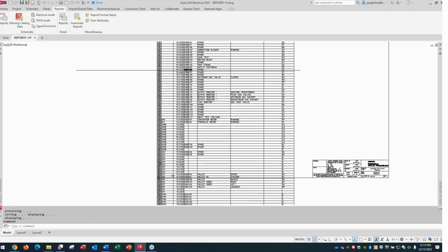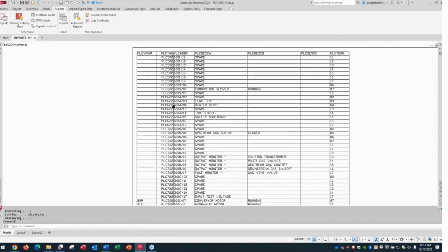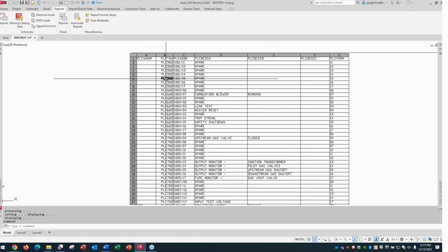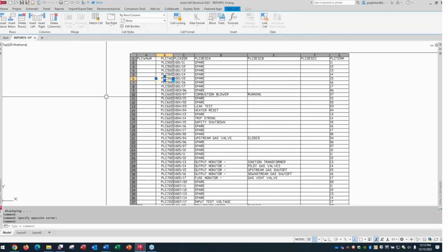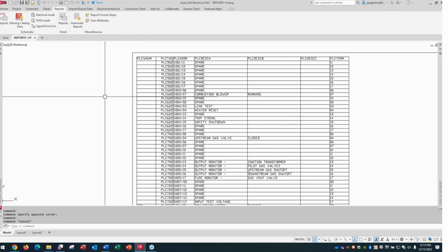This time, the text size is set to 0.18. So you can see what's very important here, which, you know, this part is not real intuitive as far as the software is concerned. Text size, in turn, the size of your table that you're going to insert is determined by the table style in the drawing.